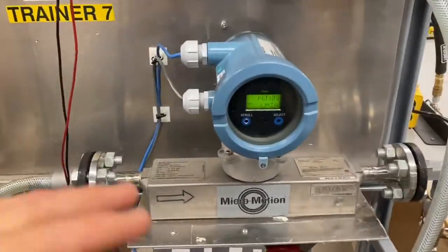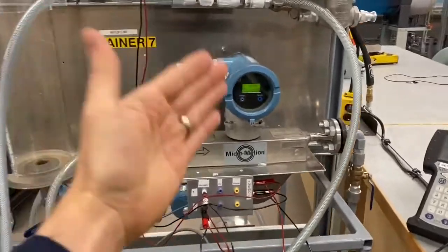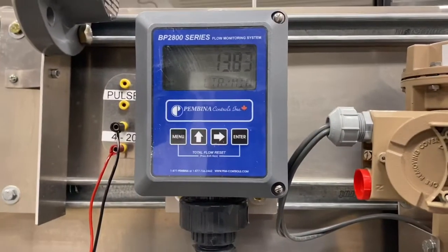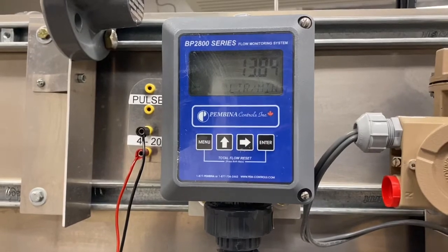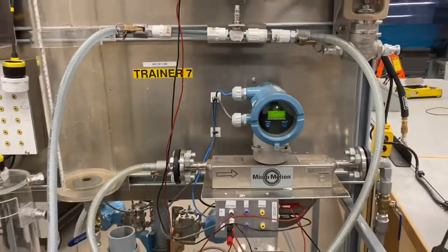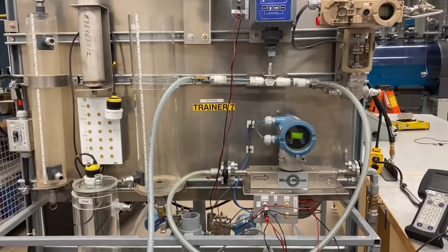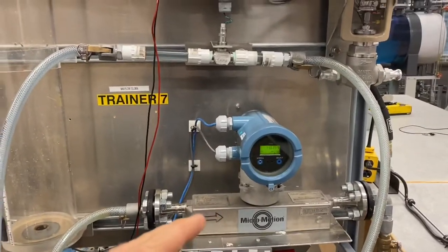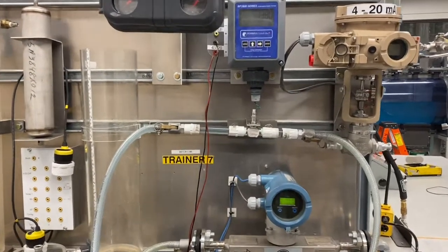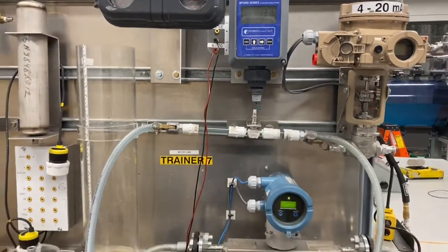So we're setting this up for a master meter prove now. We've proven this meter, we know that it's working, and now we're comparing it to the flow rate on this meter. You can see that this meter is reading almost the same, it's slightly low. So it would need to be tweaked slightly to make it read the same as our original, the one on the bottom there. This demonstrates a master meter prove. We're using a master meter, one that we know is working, hooking it in series with a meter that we're trying to prove, and verifying that they match. If they don't match, we need to adjust the meter that we're checking so that they read the same.